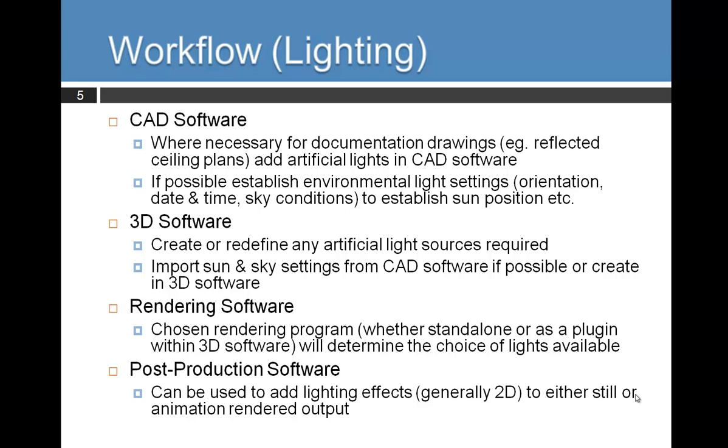Anyhow, that's probably the main consideration with rendering. Actually, the main reason people choose one rendering program over another is often, especially when you get right into it, going to be the lights. That's why I chose V-Ray, because it has such excellent lights. They're really good. Mental Ray's not bad though. It's got pretty good lights, great materials. The big strength of Mental Ray is its shaders, or materials in general.